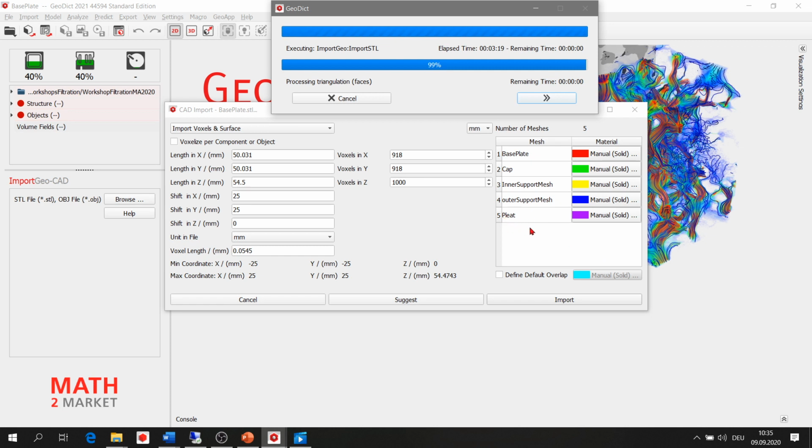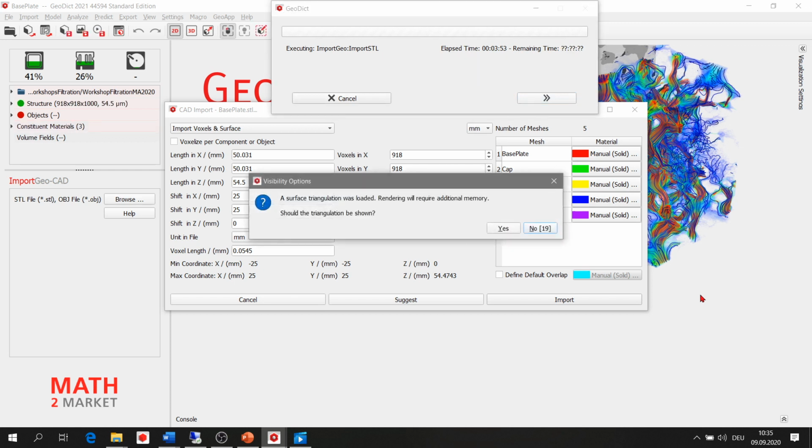And for the pleat, when you define porous media, you also have to define the permeability of the porous media, which you either get from experiments, permeability experiments on flat sheet, or you could also run a flow simulation on a microstructure of your media in an earlier simulation and then use the data later for here.